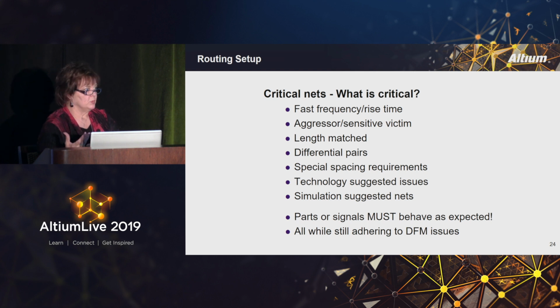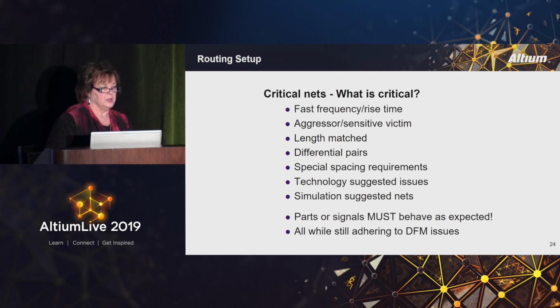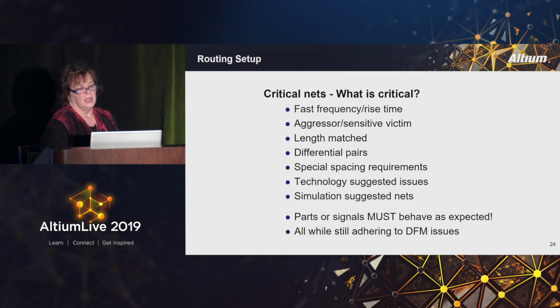Rick Hartley will tell you whether or not you need to do the length matching, and Mike did some about the length matching and some of those things that we've talked about. I'm just talking about how to implement it. If you decide that you're going to do length matching, that would make it a critical signal in my book. And I would work it out as to whether or not I needed to do anything critical with it for sure. But then if I decide, or the engineers that I'm working with decide that they want it to be length matched, then I'll go ahead and make them length matched.